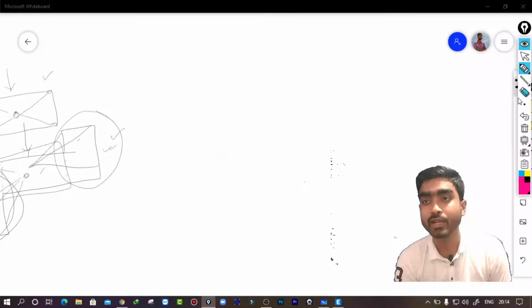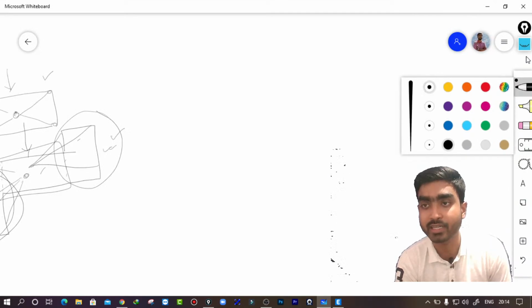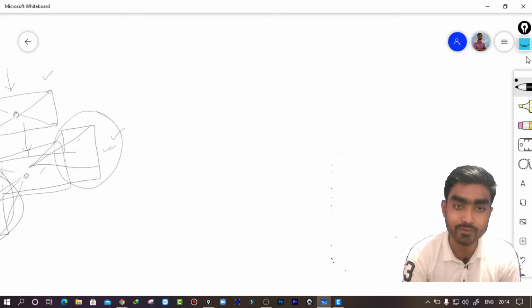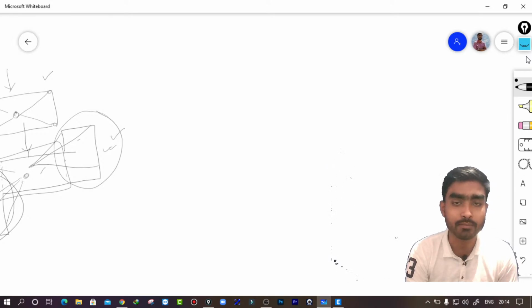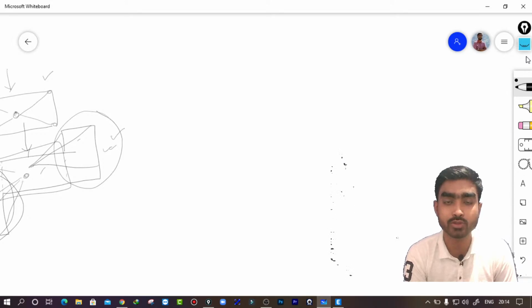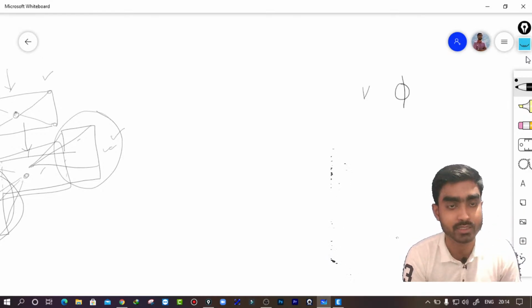So when we are checking the basic deformation under free vibration of the building, every single mode takes some amount of mass participation to create that mode shape. If you solve the K matrix and mass matrix, and you get the phi value, which is the eigenvector, then for different modal shapes we have different mass participation.